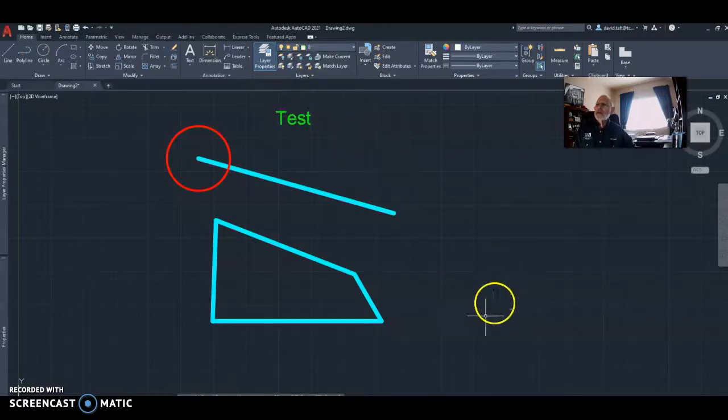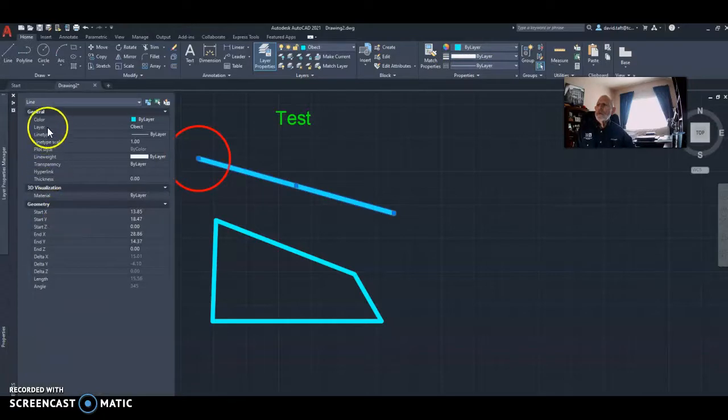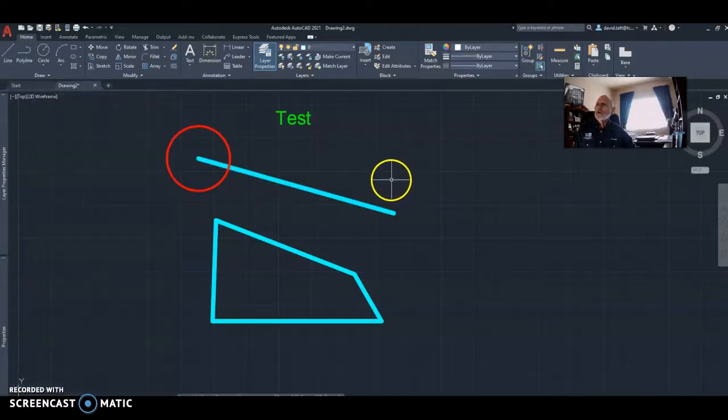So now we have all these selected, and we can prove this by selecting one of the geometric figures. Look up here, let me go back, looking up here, the zero layer is active, but if we select an object, it shows us what layer it's on here. It also shows us in the layer properties and the line weight, and of course the line type on there. So we know what layer it's on. We can always also, if we don't believe that, go to the color or to the properties and check the color, which is by layer, which is the cyan, yeah. And then the object layer, the layer that it's on is object. So there's a bunch of ways to check it, and that's one way to get things on a layer.